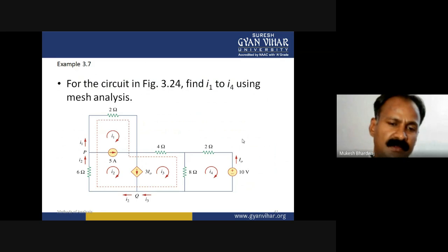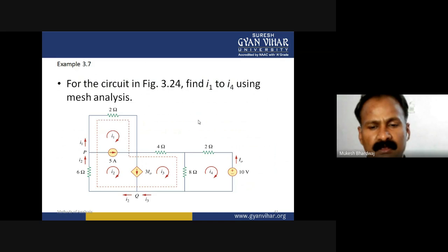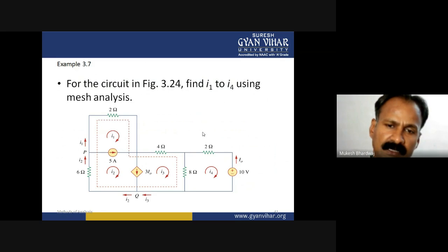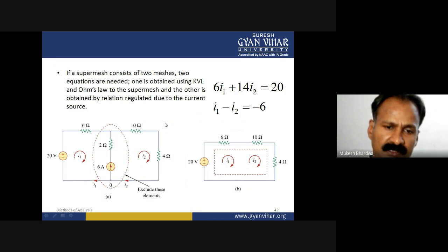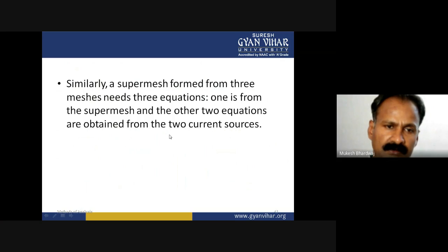What is the amount of current flowing in each mesh. So apply the mesh law or nodal analysis, frame the equations and solve the linear equations to get the values of the currents.